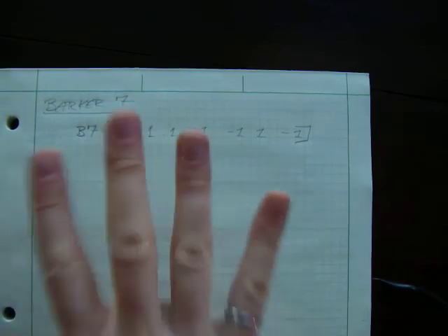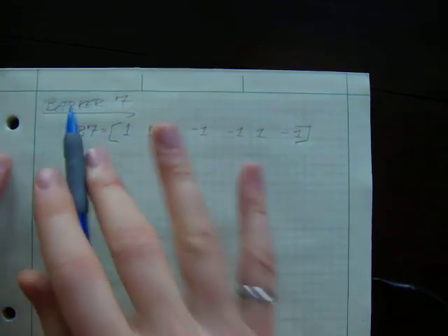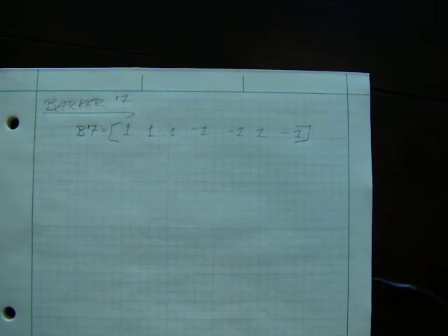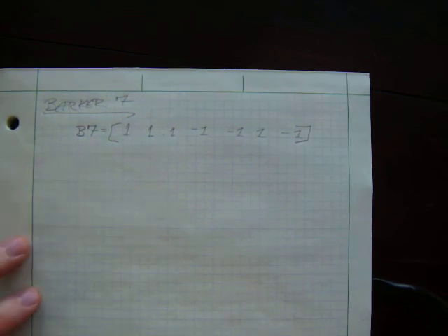There are books and books that contain different types of Barker codes and other special codes specifically formed to minimize side lobes. This is a very big area of research, and if you can find a longer code that meets the Barker code criteria, it is a huge thing, because this is what communication systems use to obtain time sync. Okay, I've got to bring up a MATLAB example, so I'll switch to the next video.